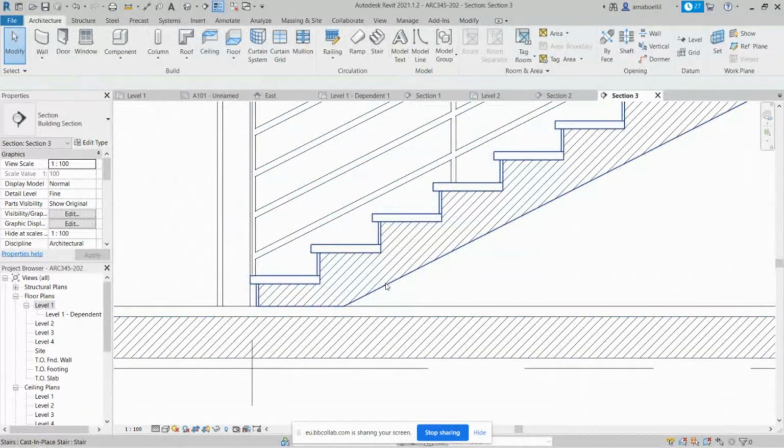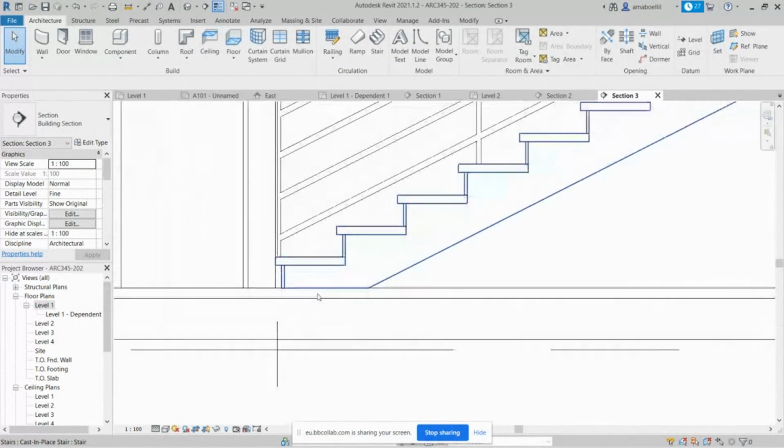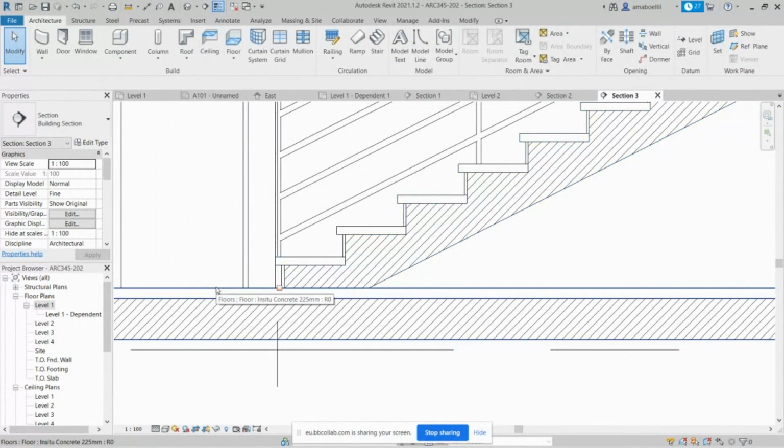Now, the connection also is something important that we have to talk about. How we treat the connection between the stairs and that. It doesn't make sense to have this as finished and the stairs resting on it. Also think about the construction. What is done first? Usually the thing that is done first is almost connected, and you have to set this properly. Do you finish the slab and add materials to it before doing the stairs? No, you do the stairs while you are casting the concrete, and then after that you do the finishes.